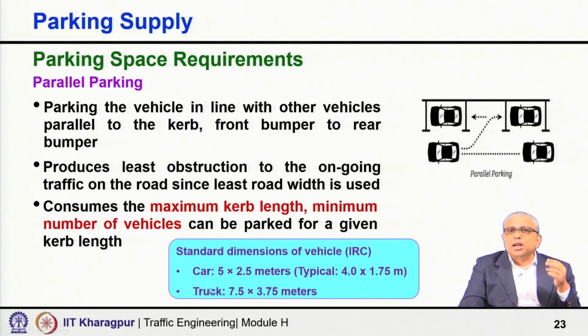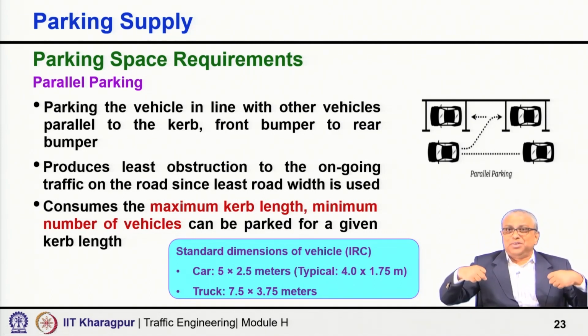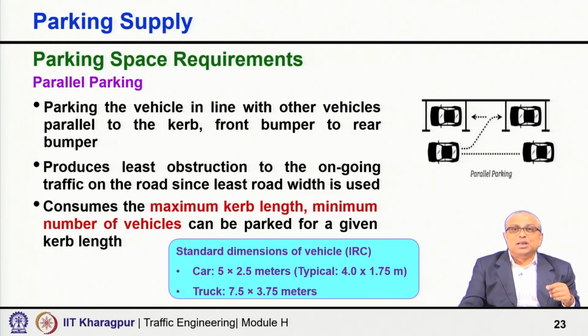Because everywhere for parallel parking, I really do not need 2.5 meter, right. You can even for parallel parking, 2 meter width would be sufficient, but if it is perpendicular or angular, yes, 2.5, because side doors will open in between two parked vehicles, right. So, you have to keep more gap, and here also you have to keep the safety, because when you open the door, it should not cause a crash, because the moving traffic stream will be there. So, all those considerations will be there.